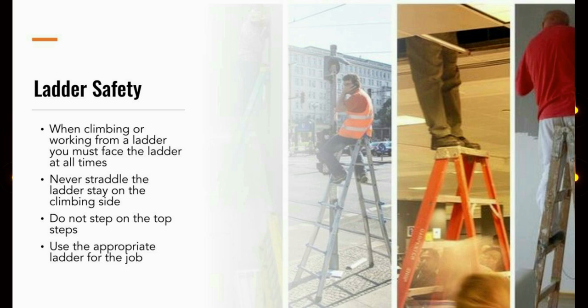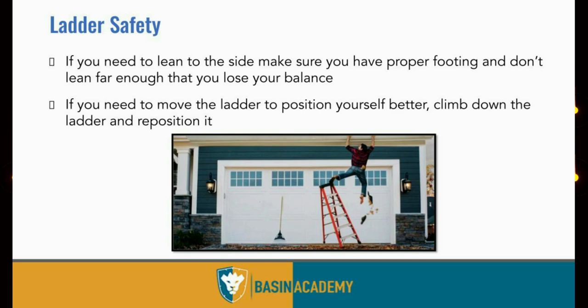Never straddle the ladder. Stay on the climbing side, unlike this guy in the picture to the left. Do not step on the top steps like the middle picture, and use the appropriate ladder for the job, unlike this guy on the far right. If you need to lean to the side, make sure you have proper footing and don't lean far enough that you lose your balance. If you need to move the ladder to position yourself better, climb down the ladder and reposition it. You'll definitely regret it if you end up like this guy is.